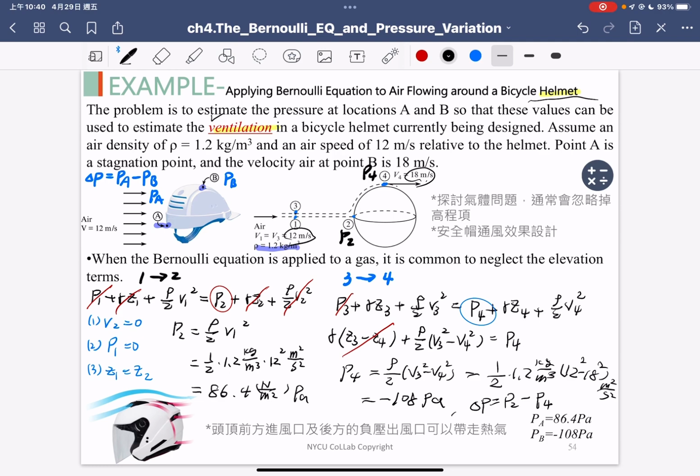Okay, so the two exercises are quite simple ideas. We just check two important pieces of knowledge. The first one, you need to double check the flow condition, whether the flow satisfies the Bernoulli equation or not. Three important assumptions are steady flow, incompressible flow, and inviscid flow, right? And the second is you need to check that the 2 points are located on the same streamline. If not located on the same streamline, you cannot apply the Bernoulli equation.